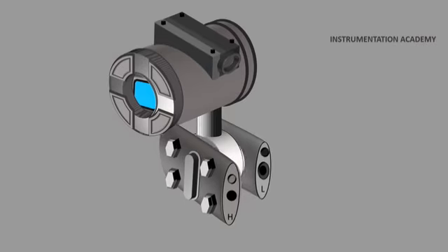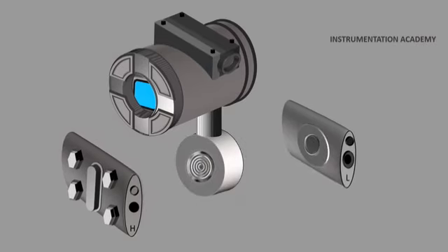The majority of industrial differential pressure transmitters are fitted with a diaphragm as the pressure sensing element. This diaphragm is a mechanical device. It is placed in between the two pressure inlet ports. By removing 4 bolts from the transmitter, we are able to remove 2 flanges from the pressure capsule, exposing the isolating diaphragms. Every differential pressure transmitter has 2 pressure ports to sense different process fluid pressures.